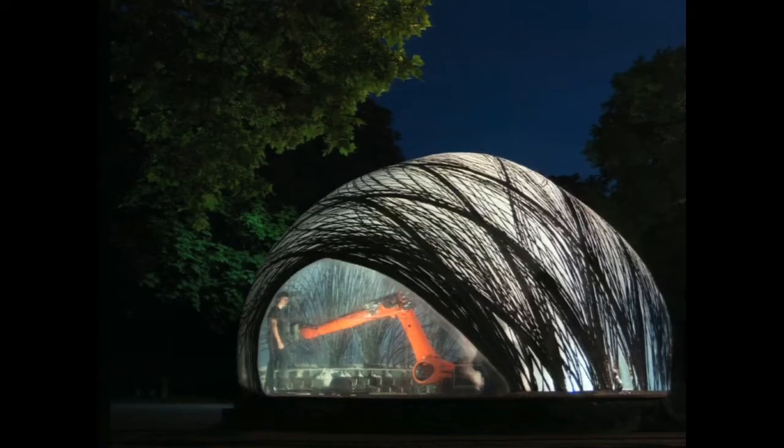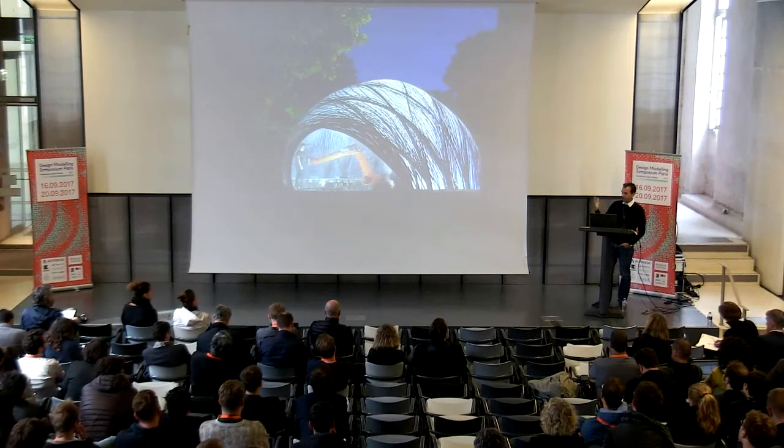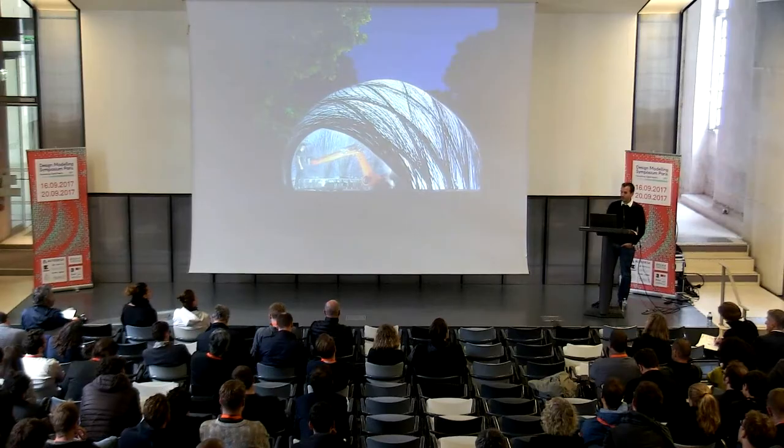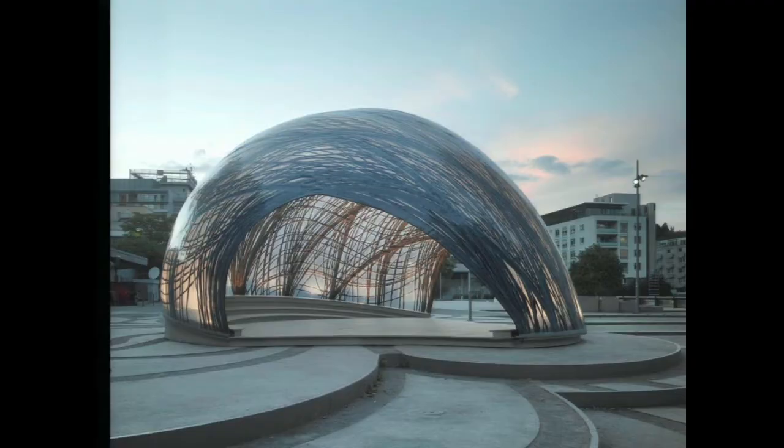So towards the end of the fabrication process, it looks like this. There is a certain order because it tries to approximate the main load paths. But then there's also an emerging random pattern because it needs to cover enough area so that there's no water sacking possible if you have more than about 10 by 10 centimeters of ETFE spanning freely in space. And then once that suitable compression state is reached, you just cut out the openings and you have a compression shell that just stands by itself.